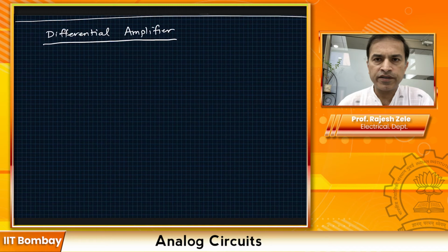If you observe the screen carefully, specifically if the oscilloscope is somewhere in the 10 millivolts per unit scale, then you will see a really large waveform going up and down on the scope. And if you hold the probe in your hand, then you'll probably see some kind of 50 hertz hum on the screen.